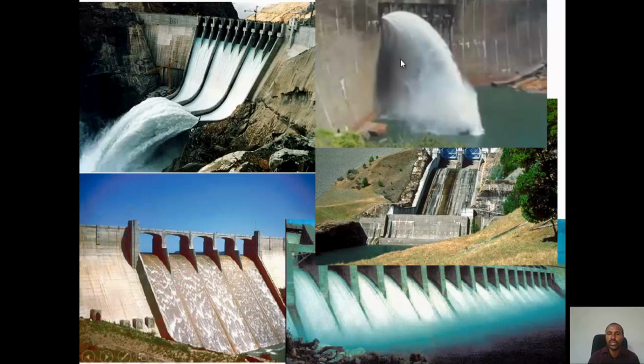And this is a vertical drop spillway. It drops, but you can provide a small bucket so that the flow goes as a trajectory motion and then hits the water. Once there is river water, there is no erosion danger. But initially you have to provide stone pitching and some erosion protection structures.